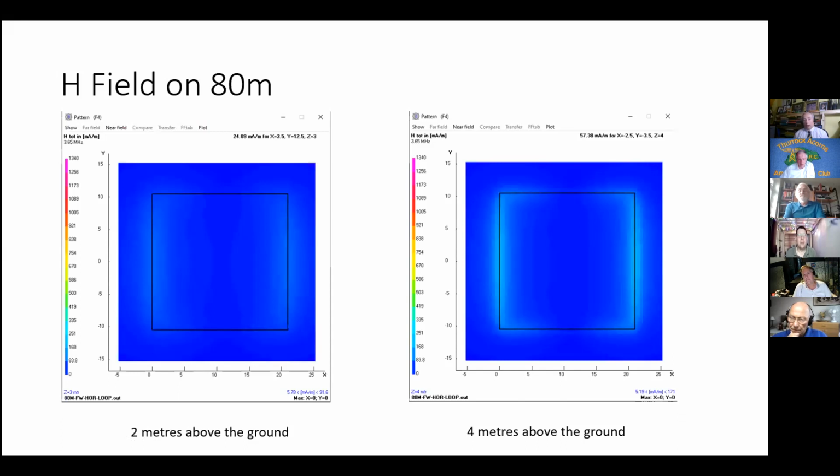Because it's a cube law that close to the antenna in the reactive near field, it falls off very quickly with distance. I think the problem you have with EMF below 10 megahertz is you can't claim averaging. Once you go over 10 megahertz, the power level you have to calculate for is the average power level, having regard to the transmit receive ratio and the modulation being used. So the distances come down very quickly because of that in practice.